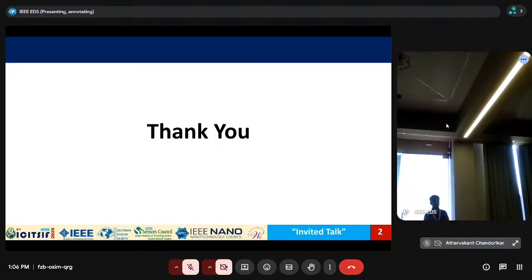Second question: are you compatible with the Raspberry Pi? For Raspberry Pi, we have to change the voltage regulator, the one that supports 300 milliampere. For its full operations, Raspberry Pi 5 requires 2 to 3 ampere of current. So we have to change the regulator IC and think of some other mechanism to turn the regulator on selectively so that it does not consume more power. There is always a trade-off. If you are using Raspberry Pi, you have to think about the regulators and other things to control that.